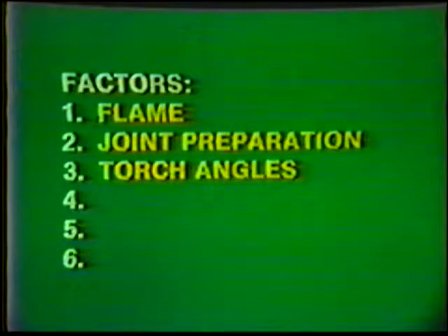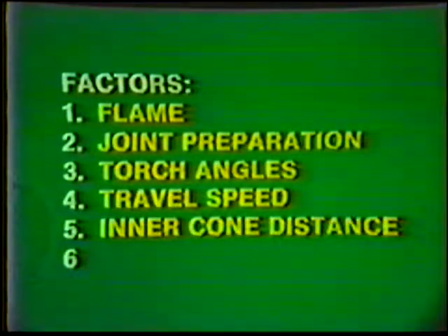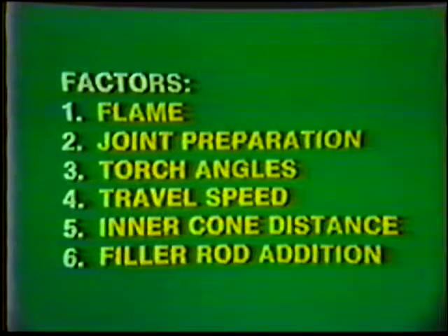There are 6 factors that must be controlled in order to make a good weld: flame, joint preparation, torch angles, travel speed, inner cone distance, and filler rod addition. Without proper control of these factors, weld quality cannot be assured.